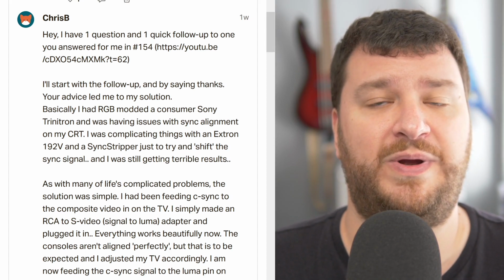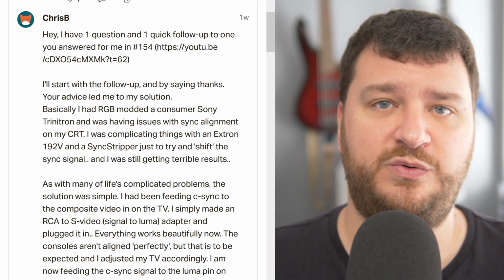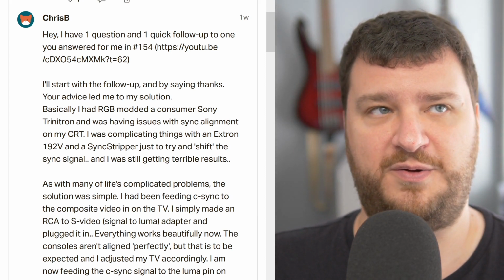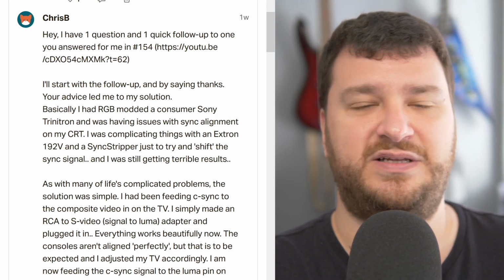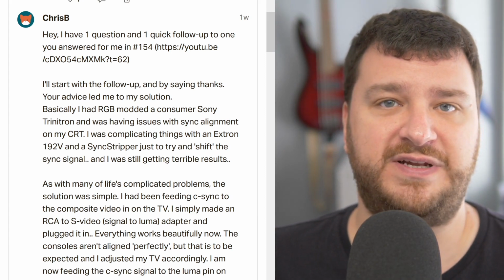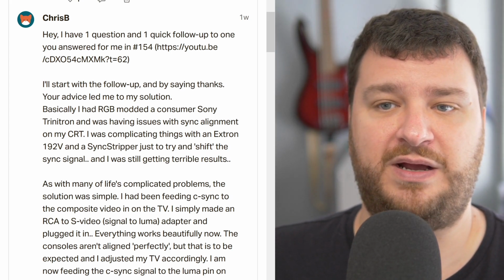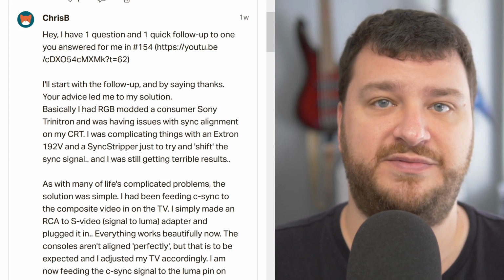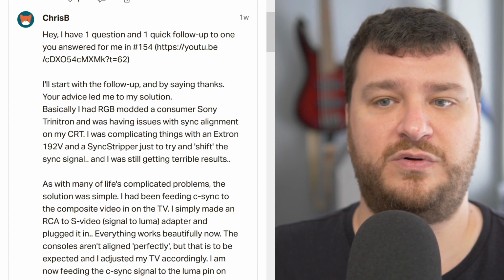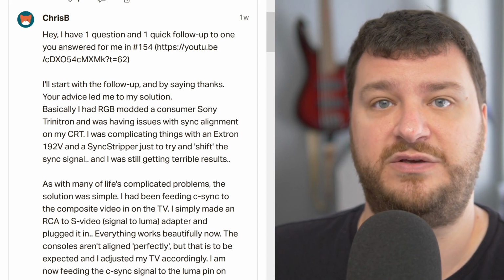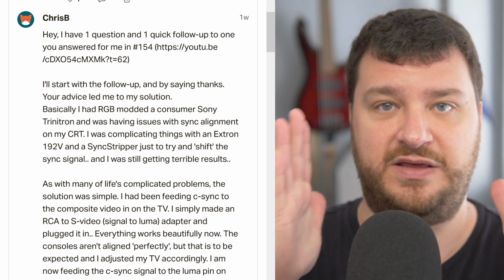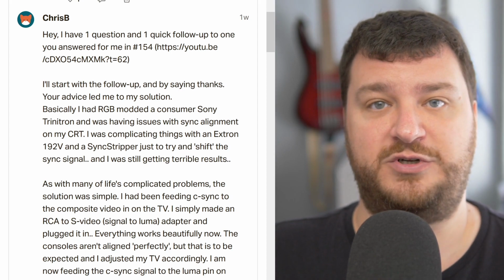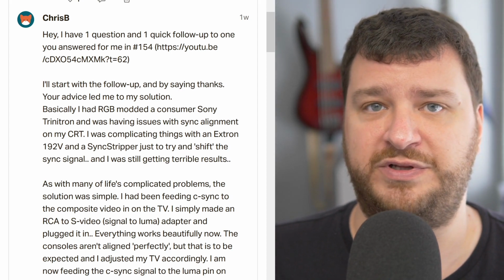But that's something that Jose found quite a long time ago, is that sometimes if you RGB mod a TV, so you're running red, green, and blue through the jungle chip that basically allows the OSD to happen, you need to feed sync somehow, and you usually pick an input to do that. So it's set to input 1, so you feed sync through composite video there. And many times that Jose used composite video to feed sync, the image was shifted over. And when he switched to using the S-video line, then the image was centered. So if I forgot to tell you that, I'm really sorry.